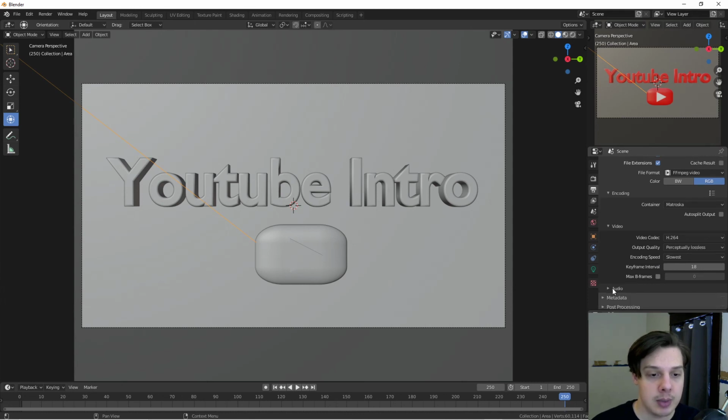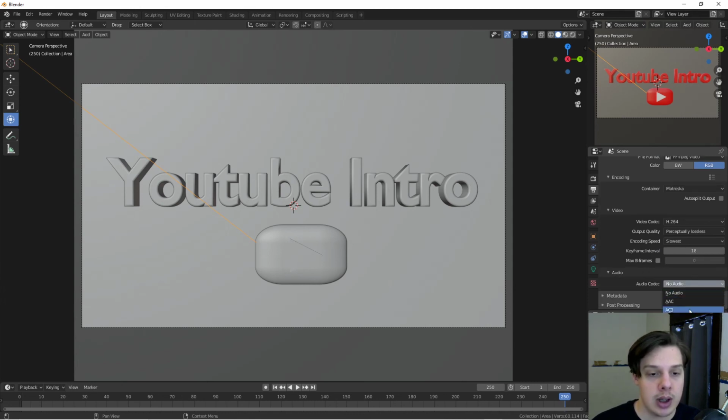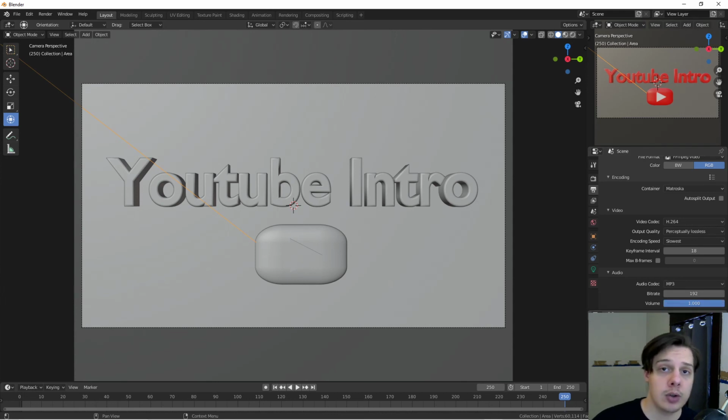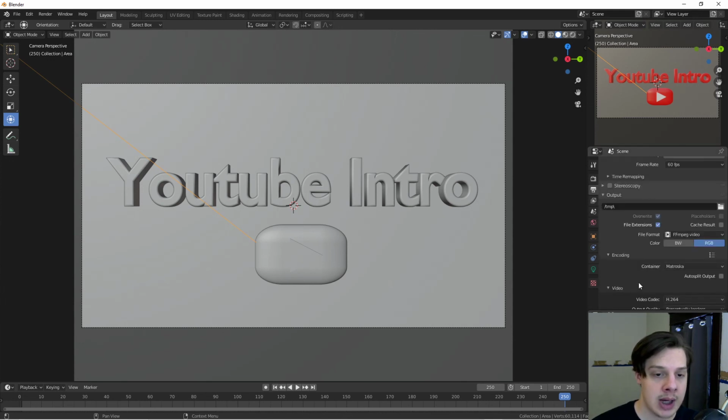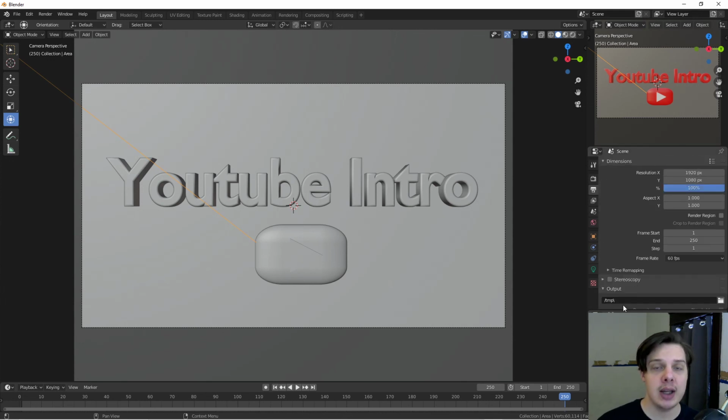Max B frames, I keep that at 0. Audio, if there's audio, you put it on MP3. If there's no audio, it's not necessarily very important for you to even select anything there. That's really more important if you're going to do something like video editing through Blender. So once that is done, you should be ready to start rendering out an animation. So to actually start that, you go to Render and you select Render Animation.